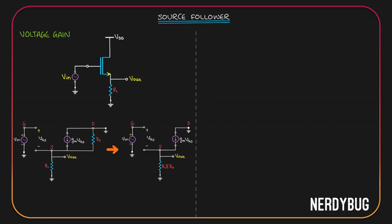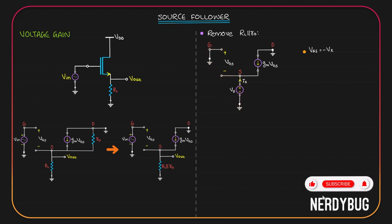Now, I want to make a simplified equivalent circuit model for this. For that, I am going to remove RL parallel to R0 first and find the impedance I can see when I look into the source like this. For that, I have added a potential Vx over here. I am trying to find its relation with Ix, which will be the current flowing like this. This is very simple. If we apply Kirchhoff's voltage law in the input loop, we can see that Vgs plus Vx should be equal to 0, which means Vgs should be equal to minus Vx.